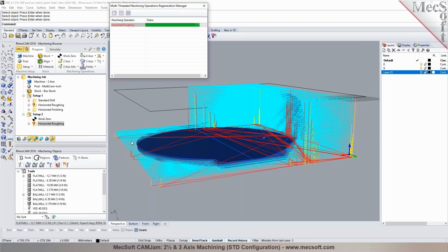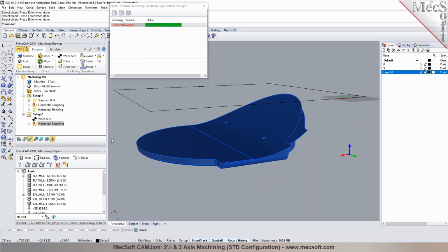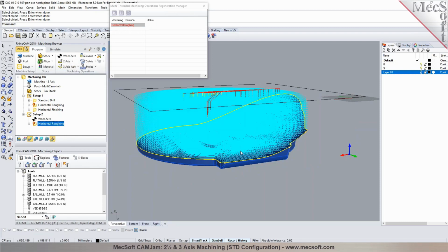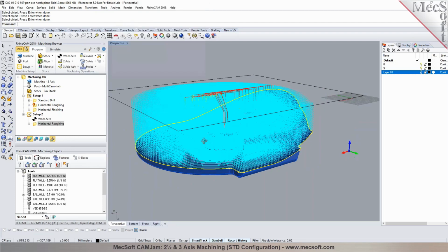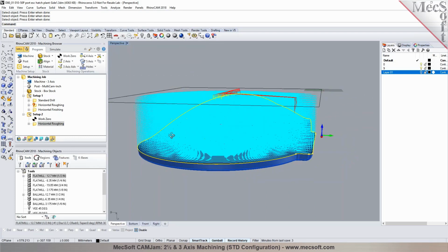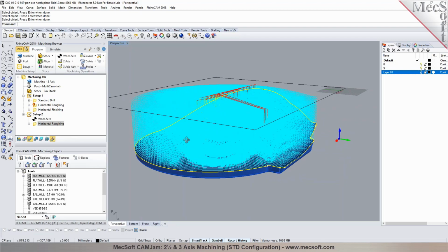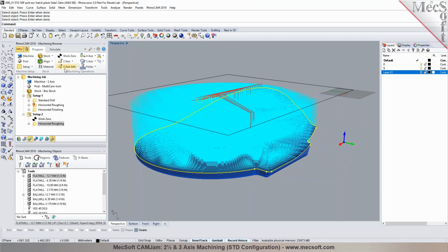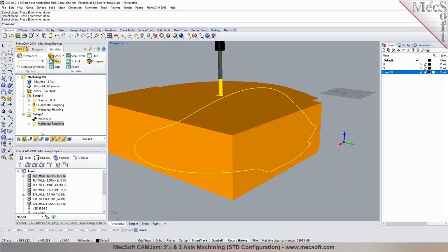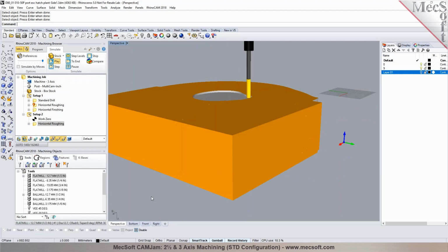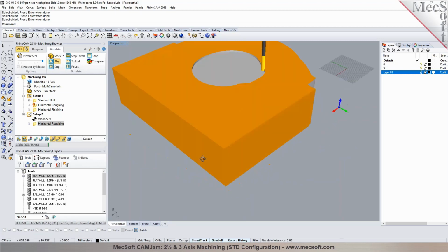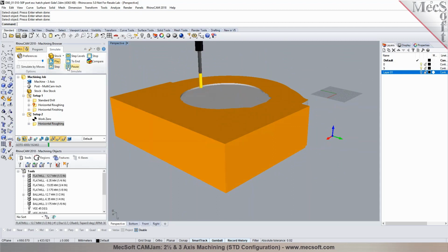Let's see. And we're looking at the old roughing toolpath. You're still looking at the old roughing toolpath. That is correct. Yeah. So it's computing it right here. This should not have any collision. And once that is computed, you can see that this is the boundary we are creating, and there's the roughing toolpath. Okay, cool. And the red is just showing where it comes above. Transfer, that is correct. Right, when it comes clear above. So basically, I'm using that as the area to contain the toolpath.